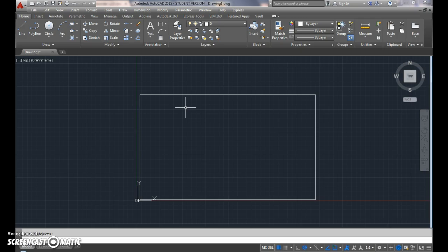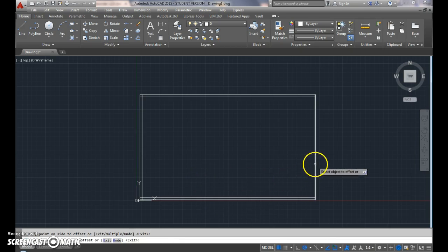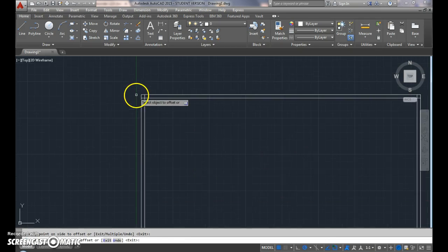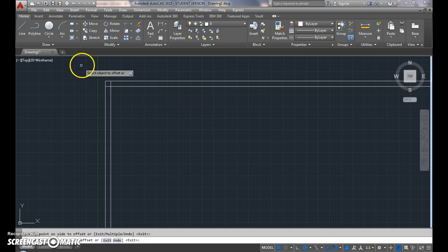Well, 6 inches is close enough for us, and really the outside measurement is the one that really matters the most. We'll talk more about modularity in another unit, but for now, what we want to do is just simply establish the thickness of these outside walls. So I'm going to start by offsetting all these walls, that 6-inch measurement. Now this offset distance is going to give me basically walls that have a material value to them or a thickness to them that I can see and relate to.